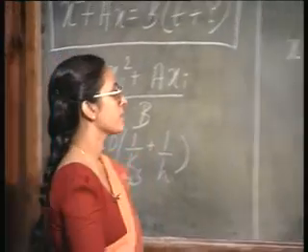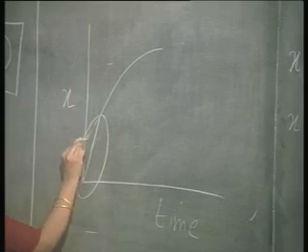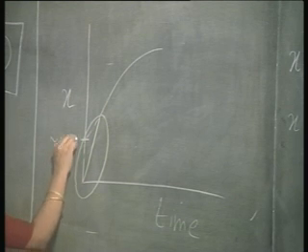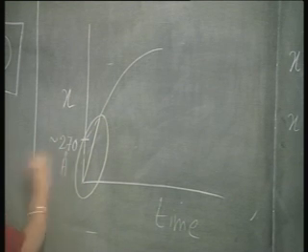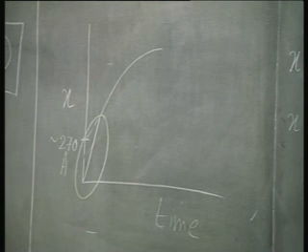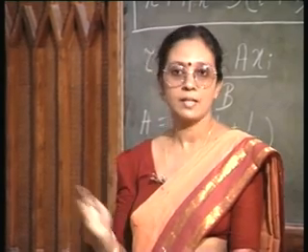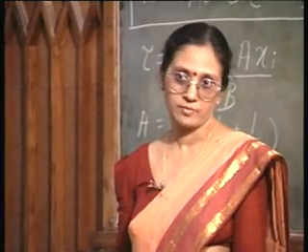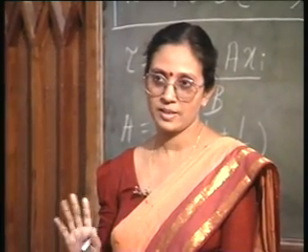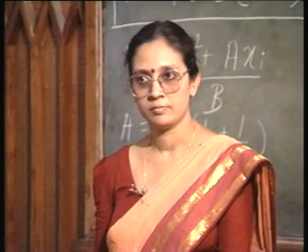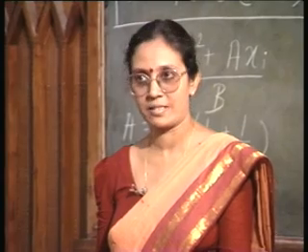This is because this intercept is about 270 angstrom. So, anything less than 270 angstrom is difficult to explain by Deal-Grove's model. Whenever you are going to an oxide thickness less than this value, it cannot be adequately explained by Deal-Grove's model. It is more difficult to predict.